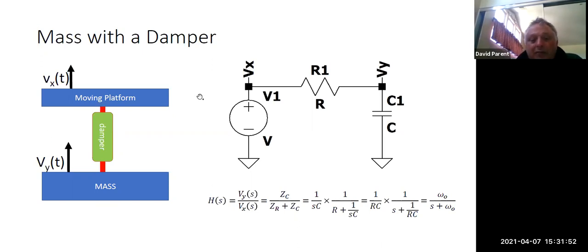And in this case, we have a moving platform, that's an input, and a damper is connected to one end of it. Well, dampers are resistors, and it's connected, right? So Vx just becomes a moving platform. Now, you might ask yourself, hey, where's ground? There's no ground in here that you can see. And that's because it's hidden. Anytime you draw this, you could just draw a fixed surface that doesn't move, and the velocity is compared to that. So you can't just have a voltage, right? It's got to be a potential drop from some known point, and so ground. So the ground is never drawn unless sometimes a fixed surface is drawn.